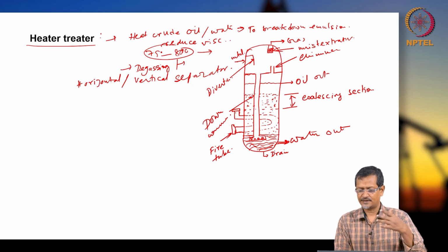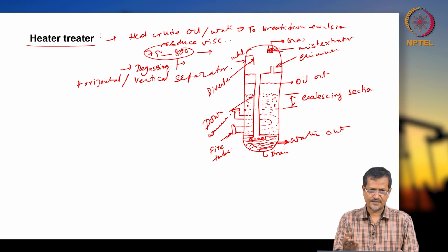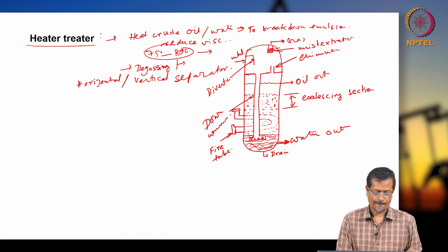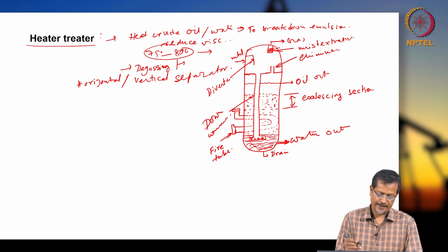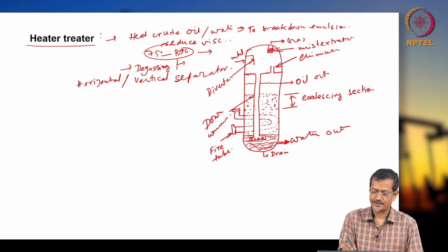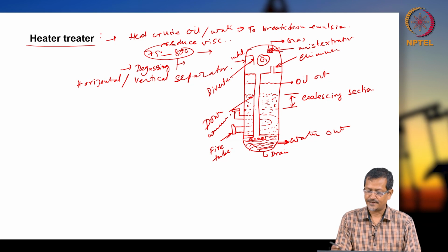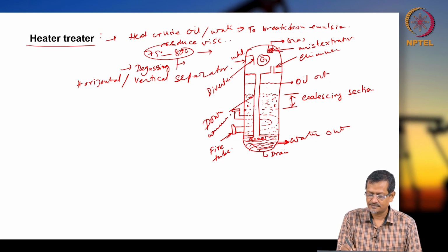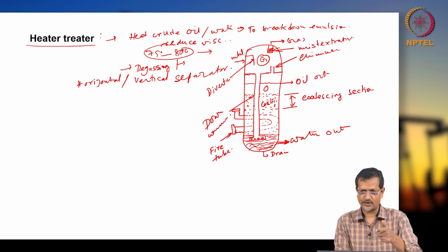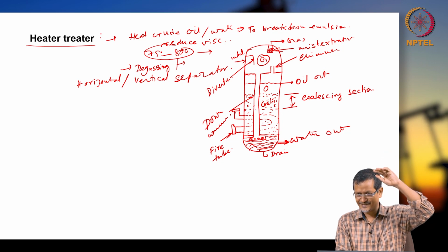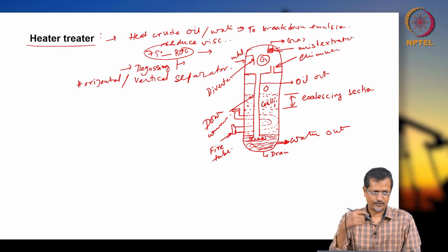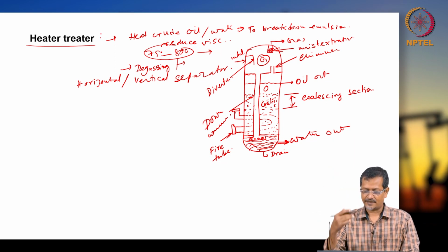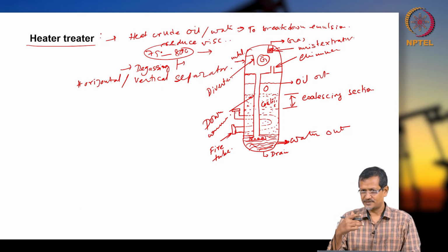And if you have any other fittings, later we will discuss what other fittings are possible. This is the simplest one. Now there are four major sections. The gas separation section, where free gas will be going out. Then this is the coalescing section, where more emulsion will be. The oil section means less emulsion. So the water particles are almost removed there, and with the water particles removed you are taking the oil out, and near the bottom the water is free from oil.